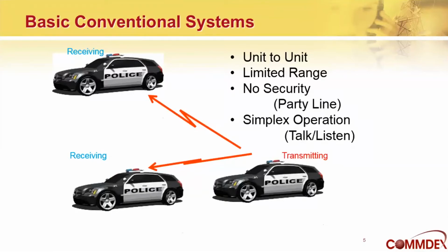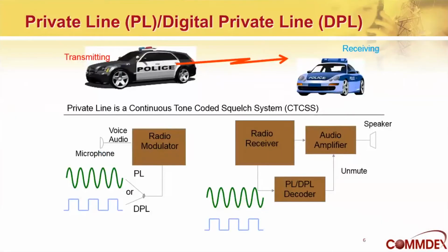You may have heard the term PL or DPL, or you may have heard the generic term CTCSS. This is a way of providing some level of privacy when we're sharing a channel. If we have several users sharing a channel, but we only want to talk to selected users in our group, then we can provide a tone-coded squelch system where we embed a signal into our voice signal, either a tone or a repeating digital signal.